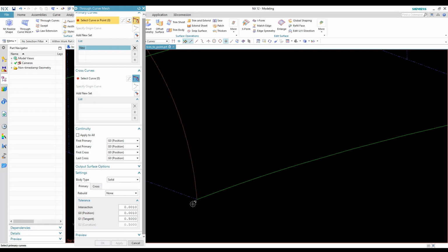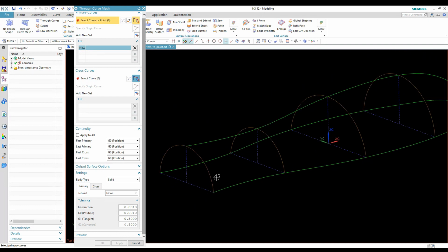What I'm going to tell you is it's better that they actually physically intersect each other and they are not off by any kind of distance, because what happens further down the line, if you start to have a surface that was created and the strings were just close enough to make the surface, you'll get problems down the line of creating the solid object that you're going to create this with, or you'll have problems with it using the shell command later.